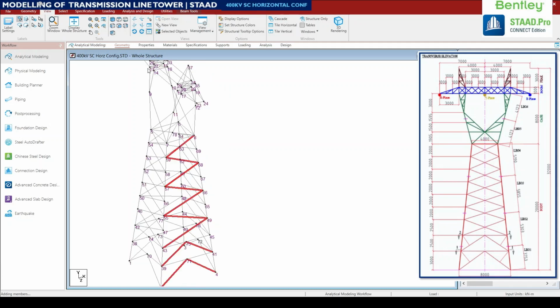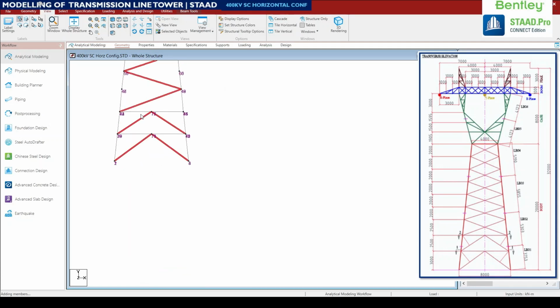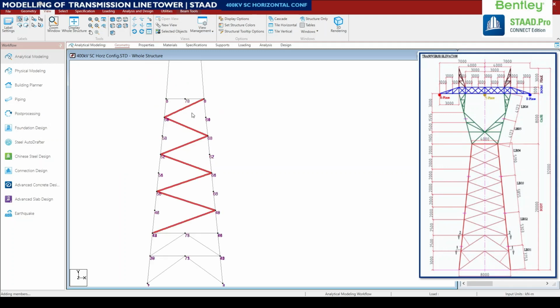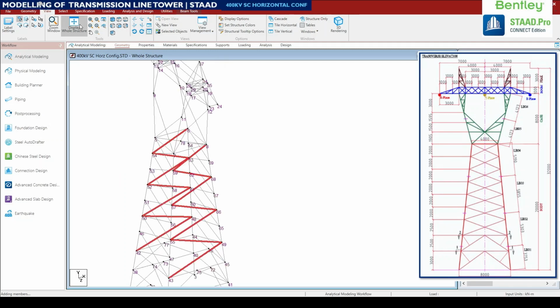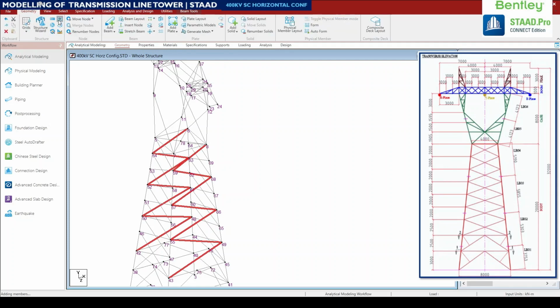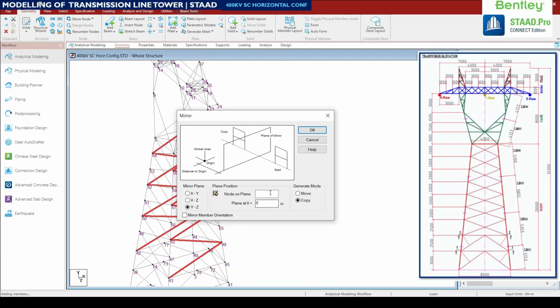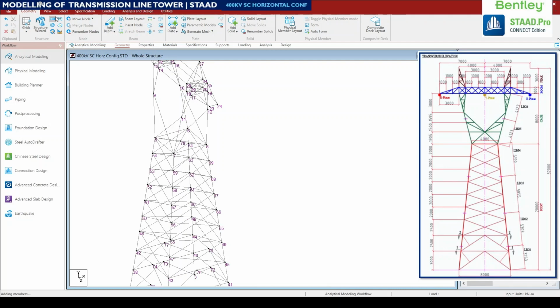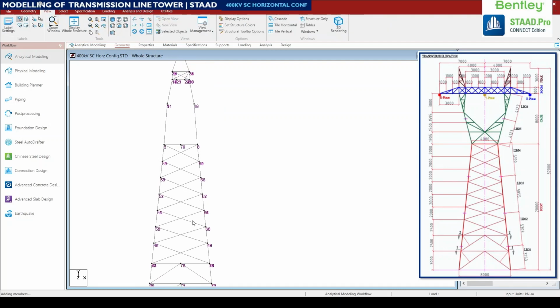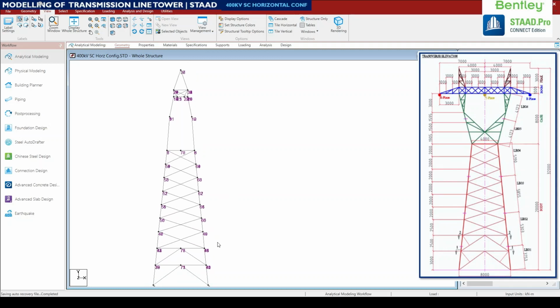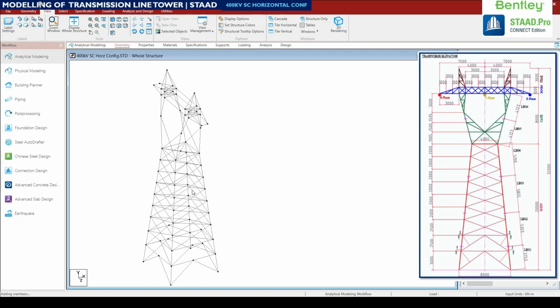Again view 3D. So here we need to deselect this. So again here geometry, mirror. So here Y and Z, node panel is 78. Click OK. So now you can view in the longitudinal direction also. So now all are in X. So now we have drawn the body.